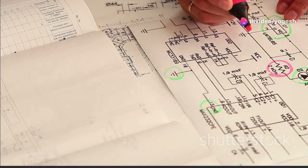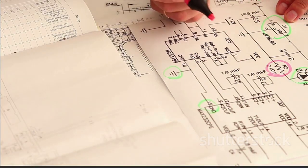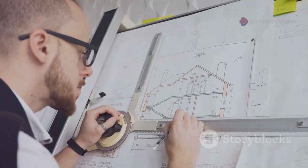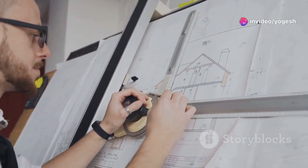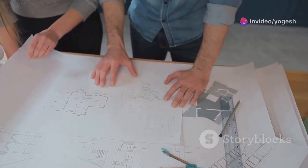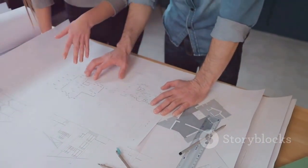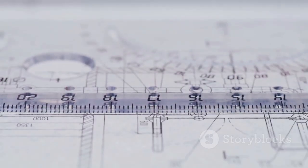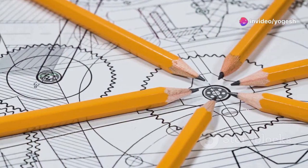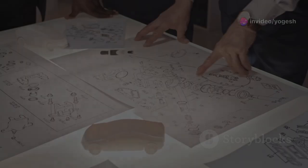We use projection lines drawn perpendicular from the slanted surface in a standard view to map features onto the auxiliary view. Then, we transfer depth from another standard view to complete the picture. It's a logical, systematic way to unfold a 3D object onto paper without losing critical information. Auxiliary views are the key to clarity in technical drawings. They make sure nothing gets lost in translation. That's why they're so powerful.